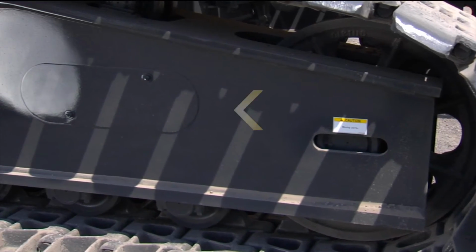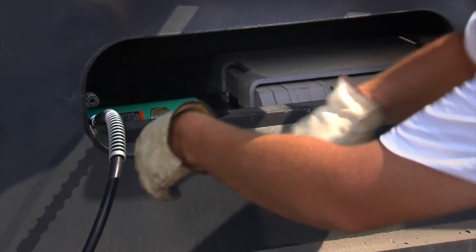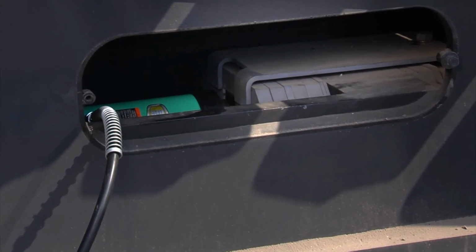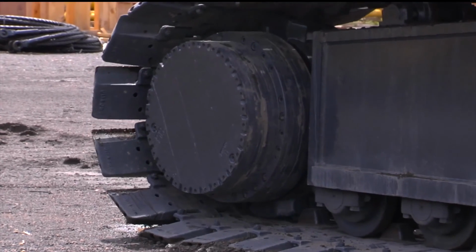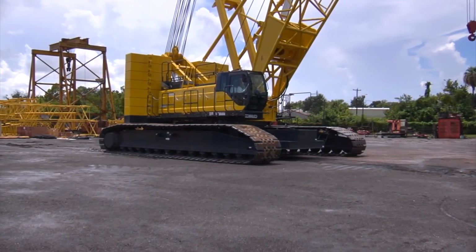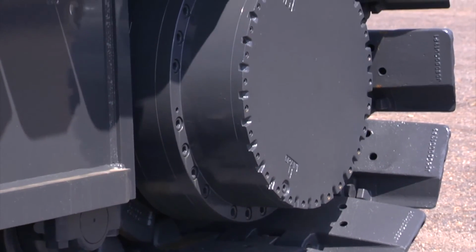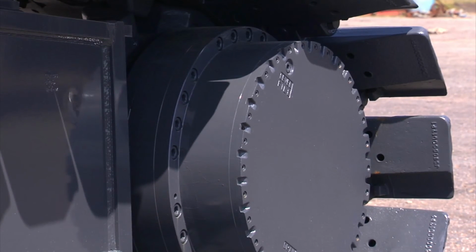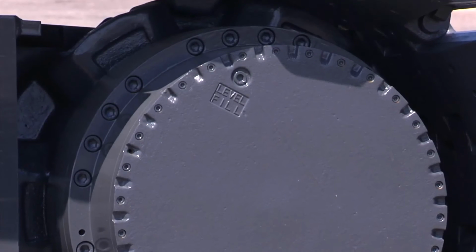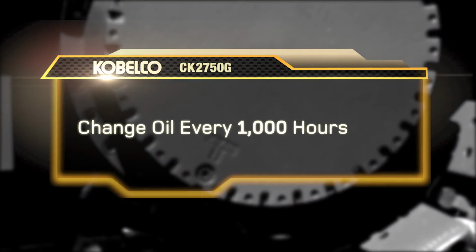The track tension is adjusted and maintained behind an access panel using a hydraulic jack and fixed shims that maintain the position of the oil-sealed front idler wheel assembly. The rear of the crawler frame contains the propel motor, propel gear reduction unit, and drive sprocket that move the fully assembled machine at 0.62 miles per hour. The complete propel assemblies are narrower than the track pads, and this aids in the prevention of damage to the assemblies from unseen obstacles during movement of the machine. The oil level in the reduction unit can be checked periodically by removing one plug and changed by removing the lower plug every 1,000 hours.